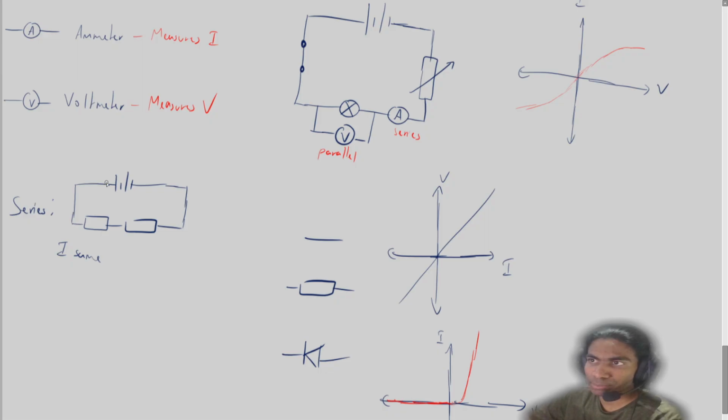However, the energy supplied, which is the packets given by the postman, needs to be evenly distributed. If both of these are identical resistors, then if this had, let's say, 6 volts, this would be receiving 3 of those, and this would be receiving another 3 of those. So the voltage is shared. Okay. Additionally, you can also show that the total resistance, RT, of a series circuit is given by R1 plus R2 plus so on. So if you have a bunch of resistors lined up, you just add them up like this, okay?